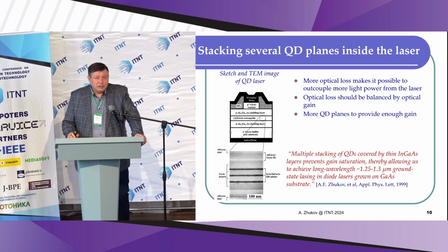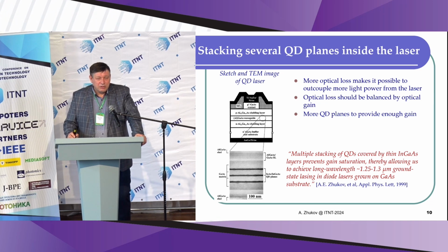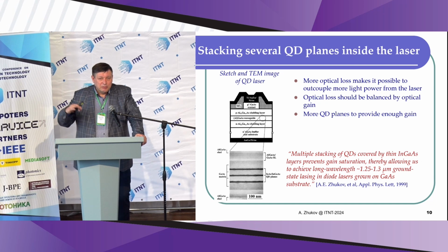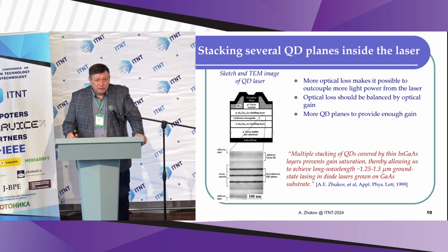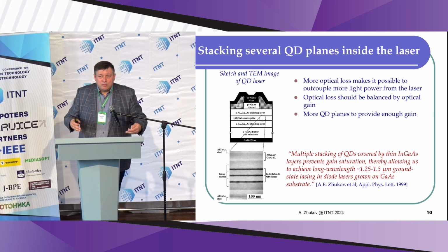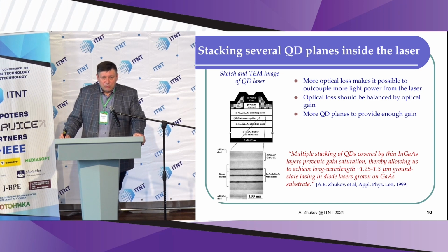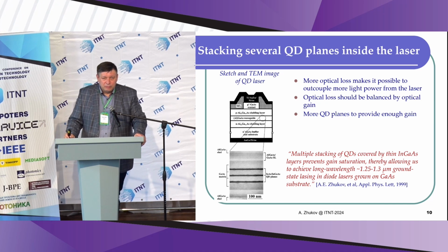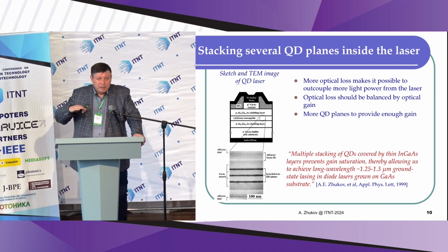Another important invention was a demonstration that quantum dots can be stacked several times. So we can use not just one plane of quantum dots, but we can stack as many as we want, depending on the application. For example, if we want to achieve very low current density, it is better to use just one plane of quantum dots. But if we need to increase optical gain, for example, to provide more optical power, or if we want to use quantum dots for detecting light, it is better to have many